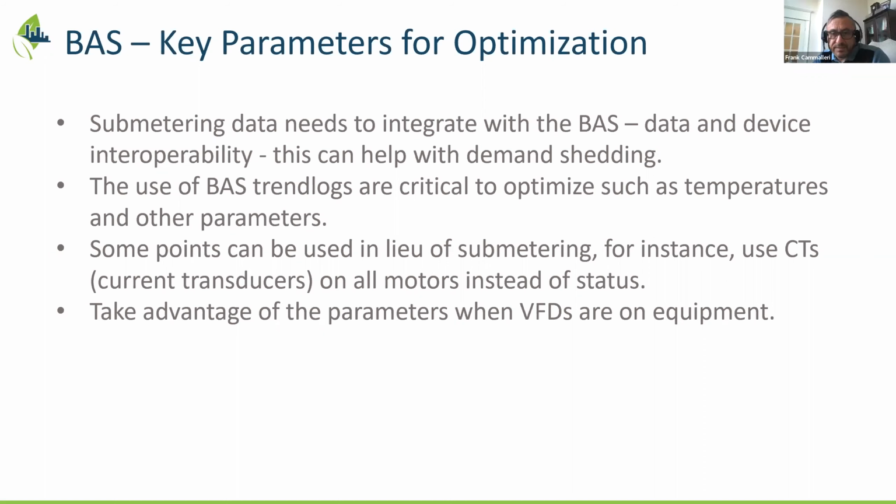And to your point about the accuracy of these things, I understand that sometimes the accuracy of the CTs is limited, but they can be used in a very useful way. An example is establishing patterns and benchmarking. If all of a sudden a motor has been using so many amps for such a long time, then all of a sudden it drops, that could be an indication that the motor's either failed or the belts have come off the fan, right?